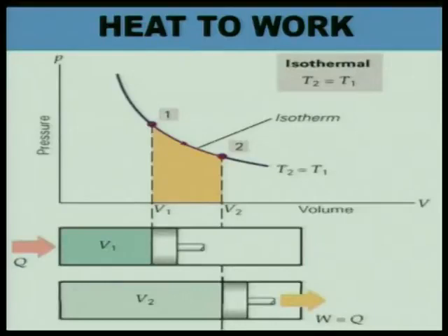In the Carnot cycle, which we will be studying also, in the hypothetical Carnot cycle, the working medium is air and the source of heat is a hot body which is outside the cylinder. The cylinder is a very good conductor, transmitting heat from the hot body to air and responsible for expansion of air. In this process the conversion of heat into work is maximum, but in actual engines this type of process is not possible at all.